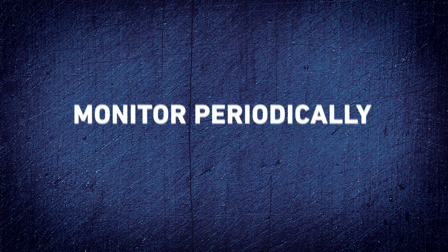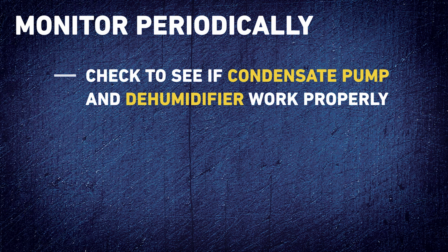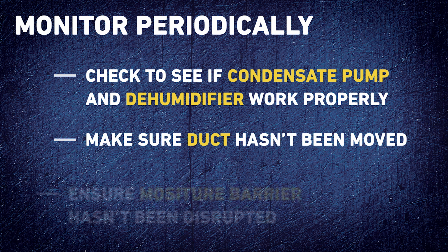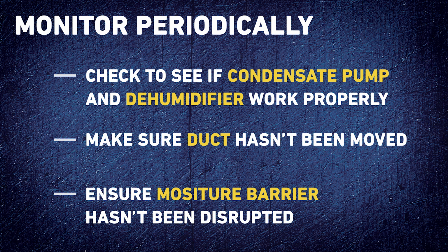Step 12. Monitor periodically in order to check that the condensate pump and dehumidifier are working properly, that the duct hasn't been moved, and that the moisture barrier hasn't been disrupted.